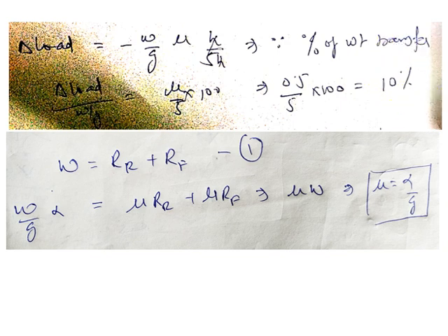So if the brakes are applied on a flat surface and the coefficient of adhesion is 0.5, the weight transfer will be 10%. You can also simplify such cases: whenever you need to calculate the load transfer on a flat surface and you are given mu, let's say mu was 0.6 and the wheelbase is 5 times h, so 0.6 by 5, 0.7 by 5, 0.8 by 5, and if the wheelbase b is equal to 8h, that will be 0.5 by 8. So this is a common expression that can be used in a number of problems.